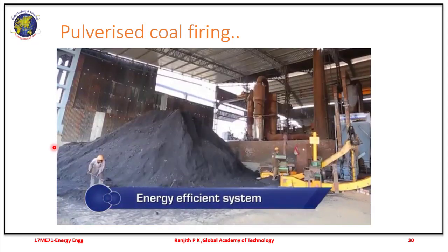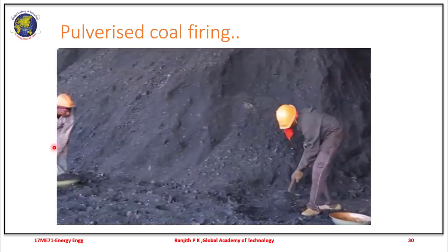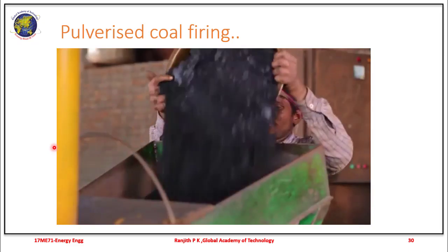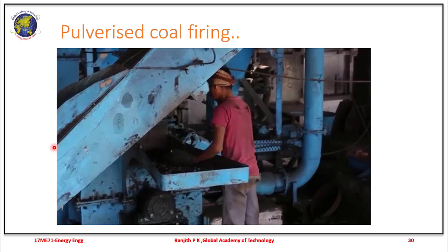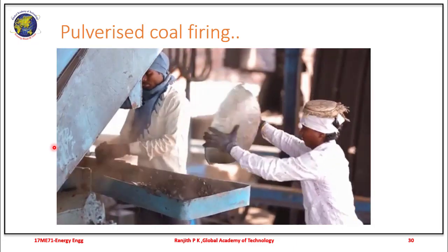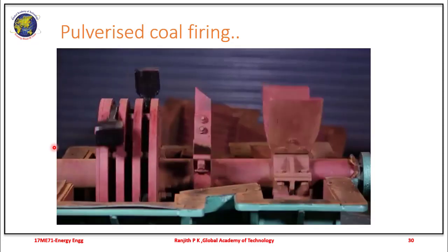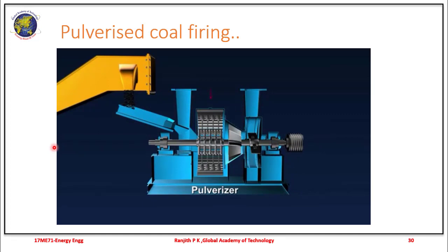The energy-efficient alternative to using pulverized coal as fuel starts with the procurement of good quality coal. Coal with high calorific value and low ash content, for example, Assam coal, is the most ideally suited for use as pulverized coal. The next step is to process or pulverize the coal into the desired fineness consistently. To do so, certain modifications in the pulverizer are required.